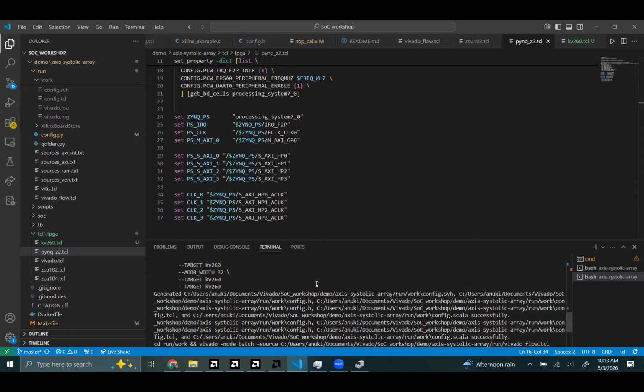Then you have to put in the Zynq command, the create Zynq processing system and set property command, so that command also you have to copy and paste from there. If you do only those two things, you can make the whole thing work for any different board. That is the idea. You might have some corner cases, but I think you can figure those out. At least most of the way you can do it like this.